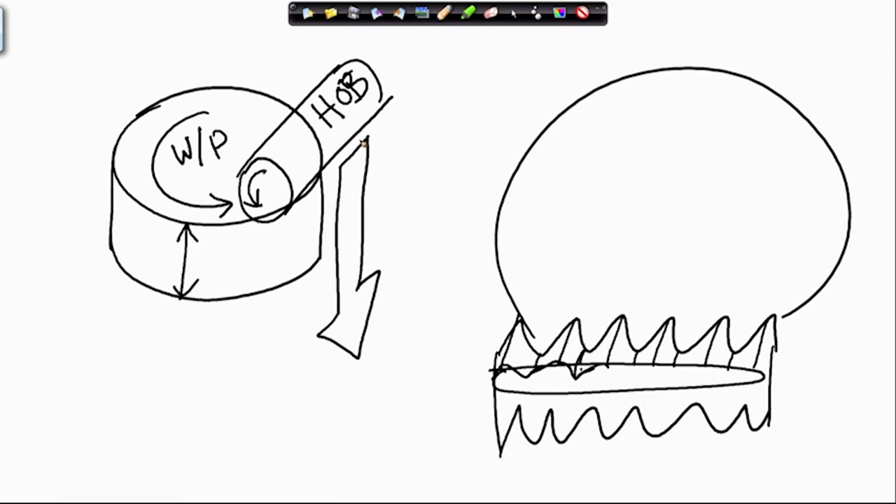In addition, if you want to cut helical threads, we need to disturb this speed ratio that they would have if they are worm and worm gears. We disturb this ratio so that the worm, instead of cutting straight down, the cut gets staggered to one side. So, for that we add or subtract an extra rotation to the workpiece. So, this is what hobbing is all about.